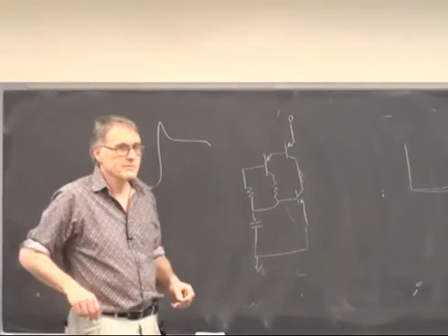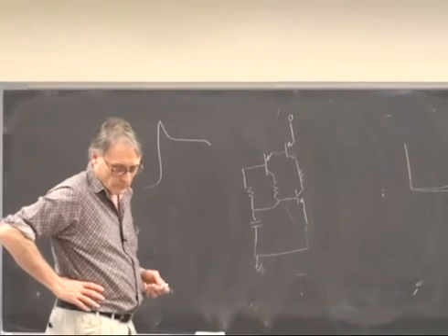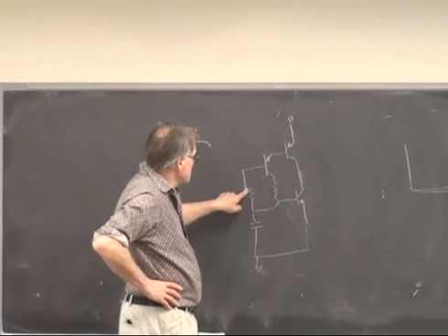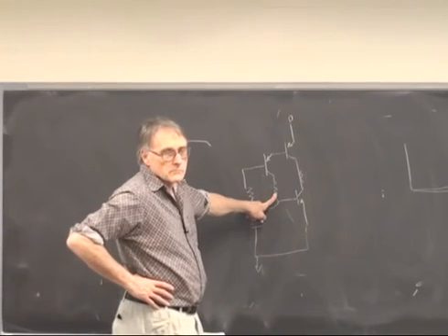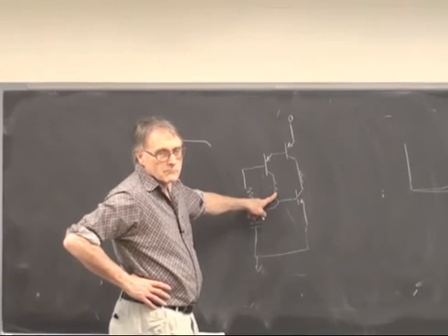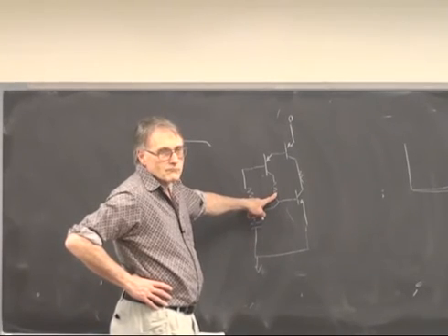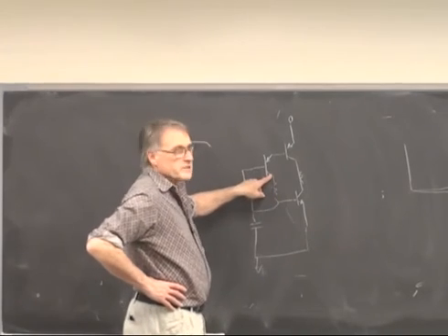So from the connection, okay, the transistor on the left hand side top. Yeah. So the output line has a resistor. No, yeah. So this is connected to the base through a resistor, right? What if that link was missing and this was directly capacitor to the ground? And where would you put this then?